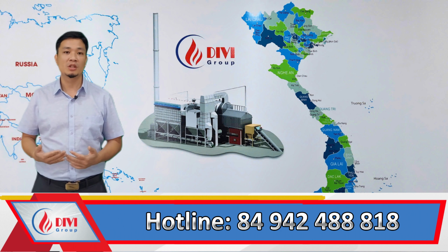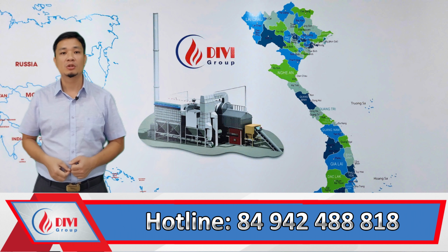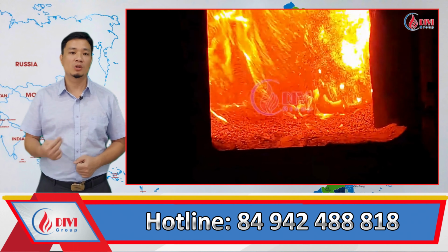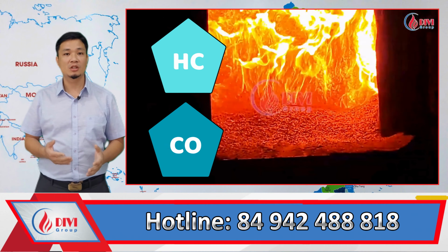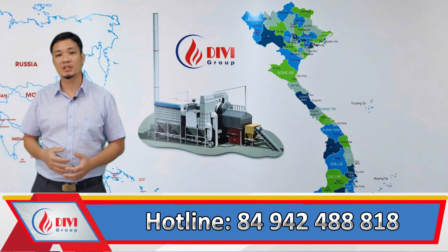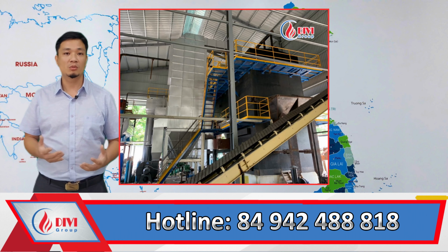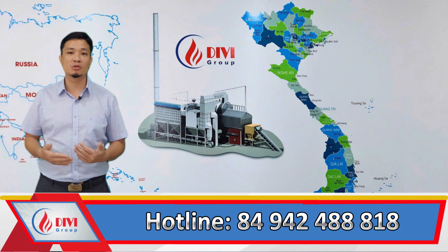The sand particles become fluidized and mix with burning fuel particles, improving the exchange between fuel and oxygen, thereby enhancing combustion. Fuel particles that remain suspended in the fluidized bed material have a longer residence time, allowing for more complete combustion and reducing emissions of CO and unburned hydrocarbons. At this point, I hope you have a better understanding of the fluidized bed material. It's precisely this bed material that gives fluidized bed boilers an advantage over other boiler types such as fixed grate or chain grate boilers.